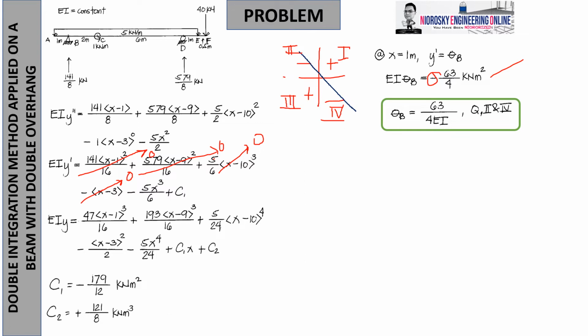So don't convert this value, because you don't have a value of EI, since it is a constant. Before, we multiplied by 1,000 cubed because the E was definite in terms of gigapascal, converting to megapascal, and I in terms of millimeters to the fourth. So, identify the unit. But when we say EI is constant, then the units are not identified but held to be true to all lengths, then you just divide it by EI without conversion because you don't know the proper unit of EI on that specific problem. So, the answer would be the constant over EI.